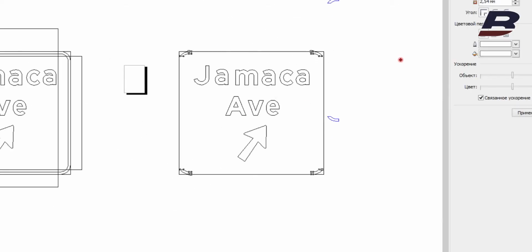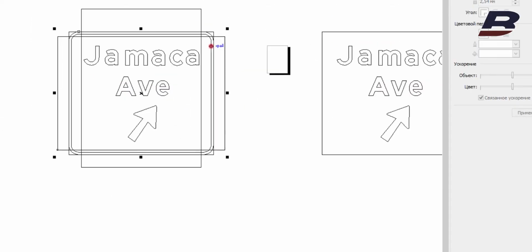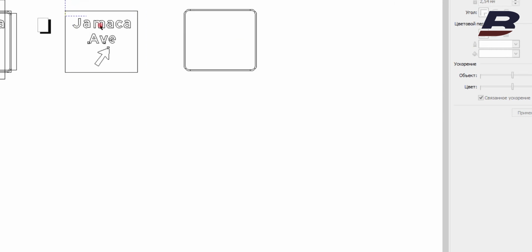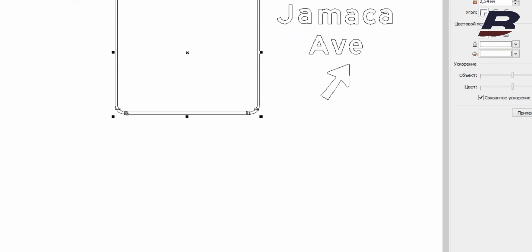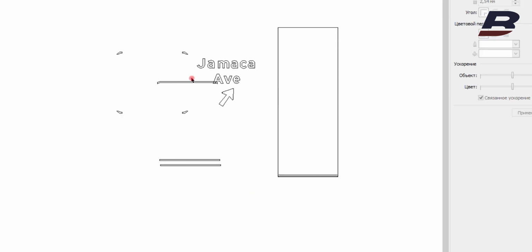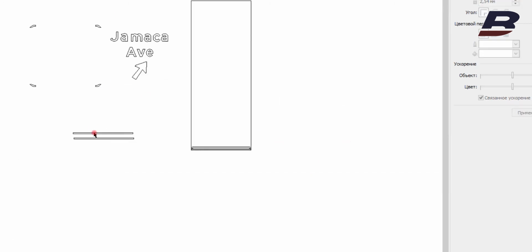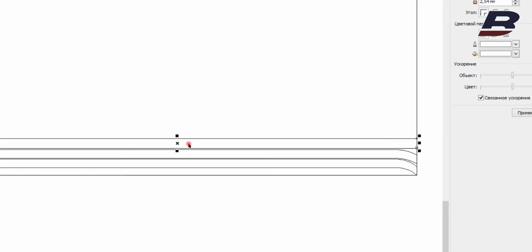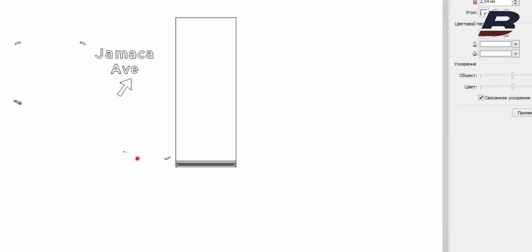Design and cut job. How would a normal, adequate designer cut this image? The standard width of a microprismatic roll is 48 inches or 1.22 meters. I prefer to work with 0 and 90 degrees orientation because of simple logic. Almost all letters of the alphabet, especially capital letters, perfectly fit in a rectangle, right?